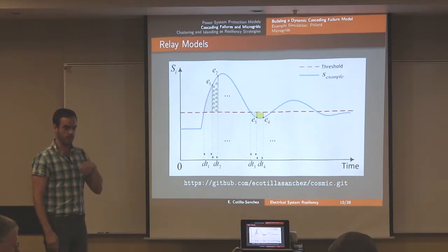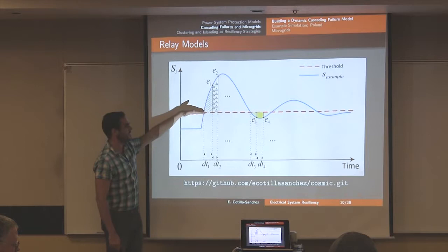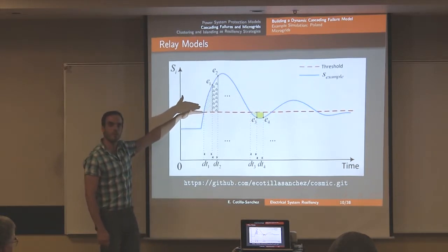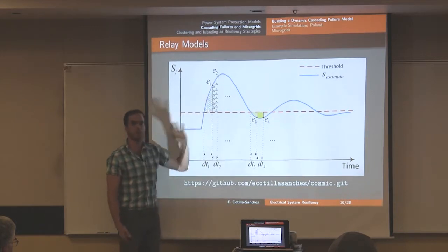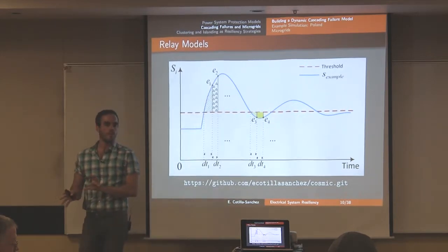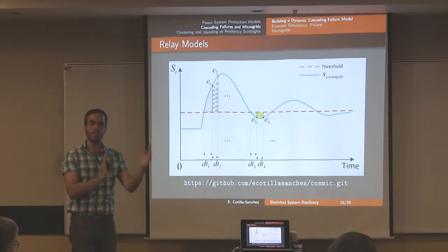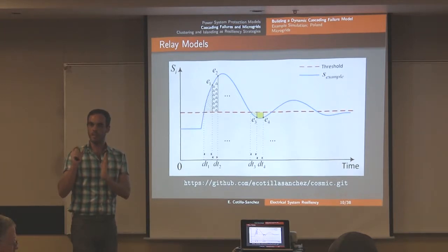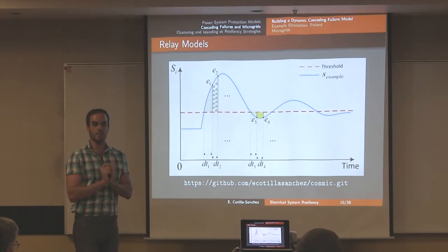relay models. So we have distance relays. In this case, instead of having just a static threshold, if you're looking at relays that tell you how far you are from the threshold, it's really tricky to combine that with, for example, a commercial software like PSSE, because you have a fixed step integration size, a step size. So it's very hard to integrate things that we know about relays and match those with how commercial software sometimes does the math in your integration step size.